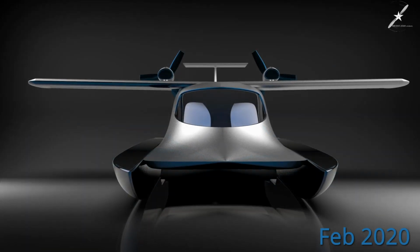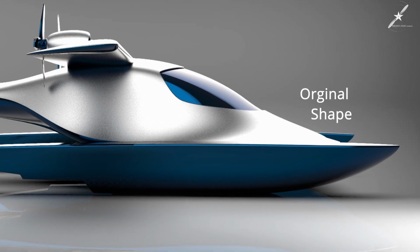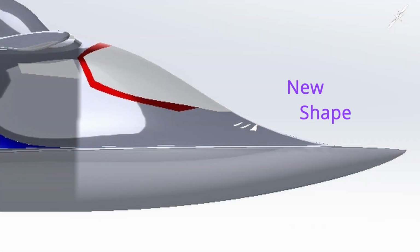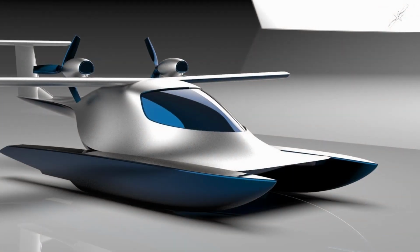Once I received these photos, we got to work. Lots of things needed to be changed. The first thing I wanted to change was the side profile curve of the nose. After that, I thought I wanted to change from the original round nose to a flat nose. The reason I changed it to a flat shape was because I started thinking about the stresses the pontoons would encounter in rough water on takeoff and landing.